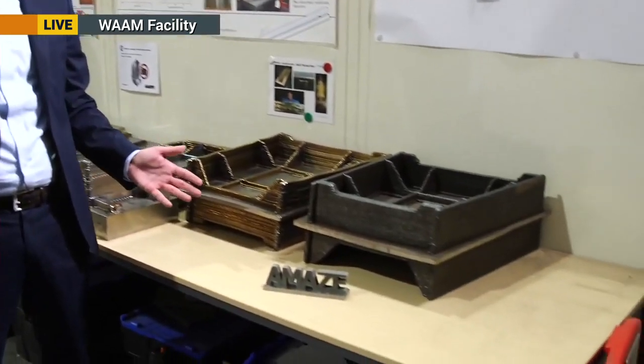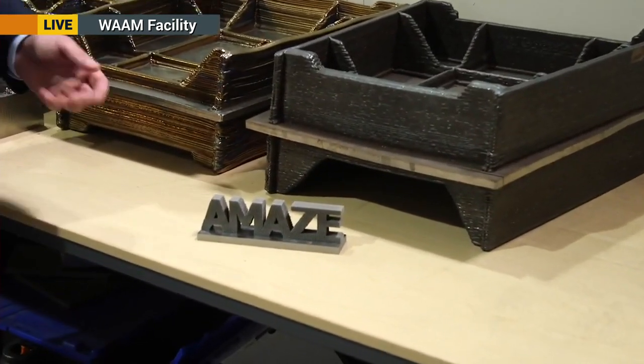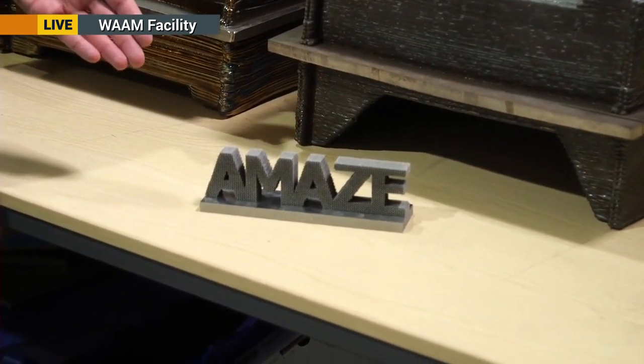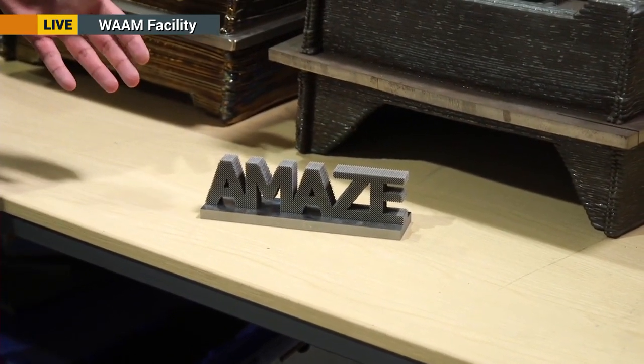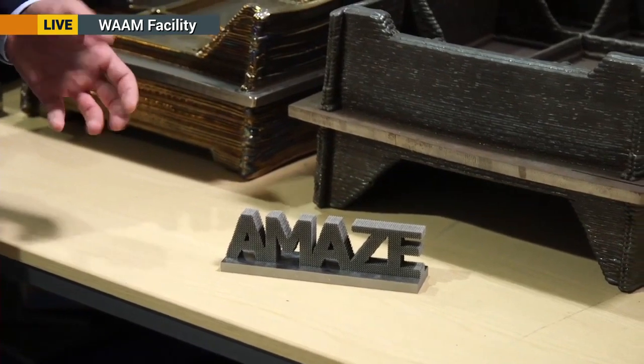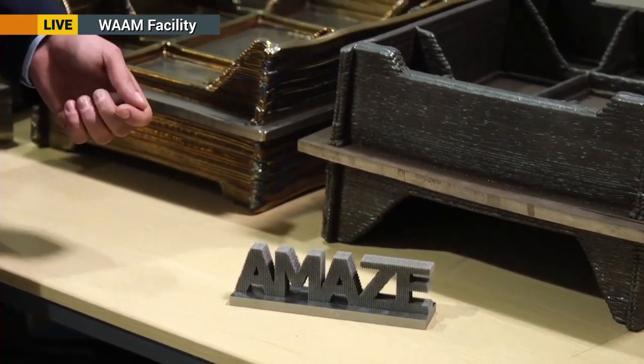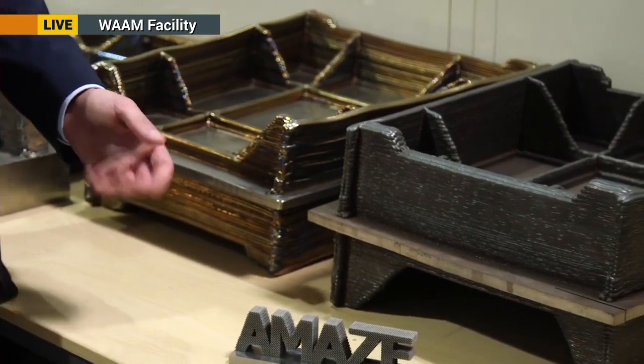And if we combine these three in a number of ways, we give origin to a wide range of processes. For example, we can look at processes based on a bed of pre-placed powder, which by using a laser heat source can generate highly complicated, optimized structures which are net shape. So in theory, the geometry is exactly the one you want it to be as soon as the manufacturing process is finished. However, these processes are extremely constrained in terms of cost. Machinery is expensive, raw materials are expensive, and also speed and size, which are both very, very small.